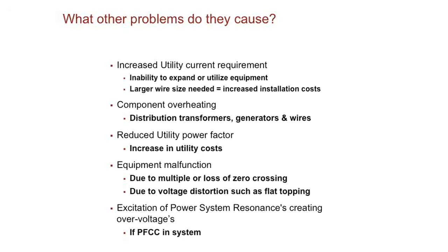So why do we care about these harmonics? What problems do they cause? Harmonics can cause you to increase the overall system size, right? That transformer has to supply the fundamental currents, also has to supply the harmonic currents within your system. If you want to think of the harmonic currents as waste in your system, that's what it has to supply.